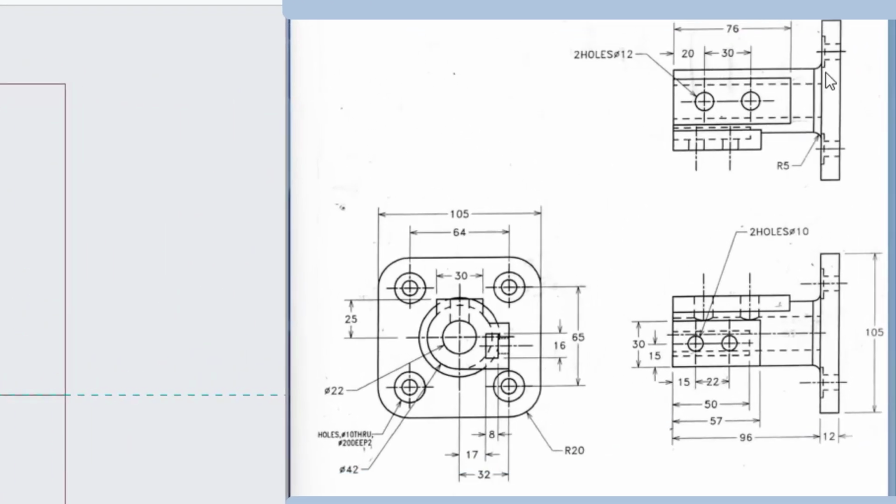So this is a shaft kind of thing with a round here, and the dimension of the shaft is given on the side view. You can see the side view where the 42 is the dia. And the other circle, the outer circle seen, is not a dia, actually it is the round. The junction is rounded, so that is what you are seeing in the outer circle. So only 42 is given as the dia, that is the shaft dia, and then dia 22 is there, which is the hole dia. So first we will try to do that.